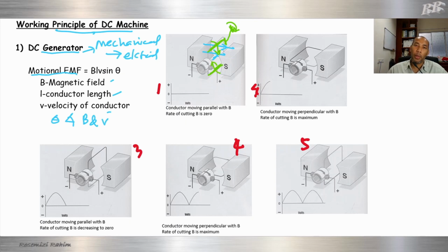What happens when this conductor rotates? Based on Faraday's law, the moving conductor will cut the flux. It will cut the blue color, the green color. When the green part moves, it will cut the flux, so there will be an induced EMF, and we call it induced current in the conductor itself.